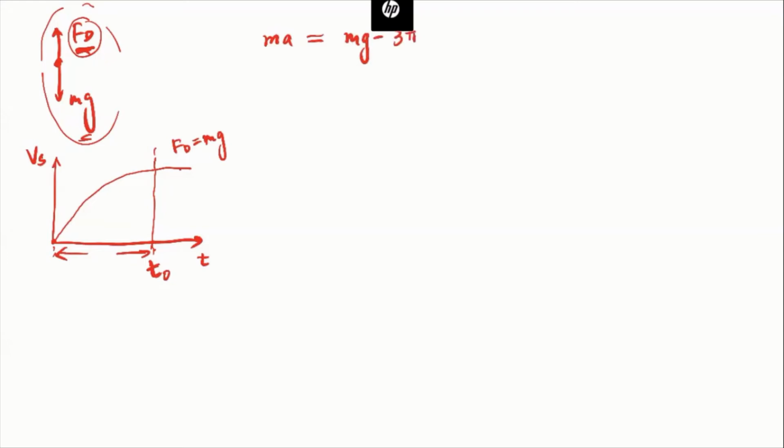Drag force is 3 pi mu dp multiplied by v divided by c, okay? Because the air here, we assume is stagnant air, so the air doesn't have any velocity. Because of that, the relative velocity is just the particle velocity, right?